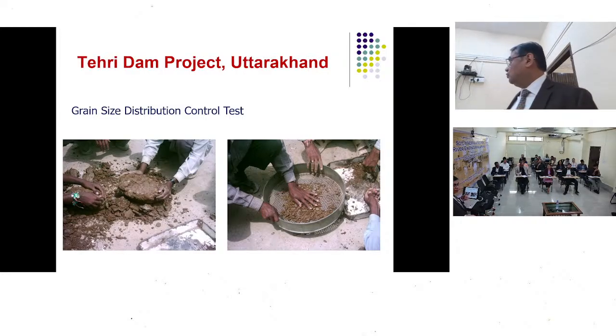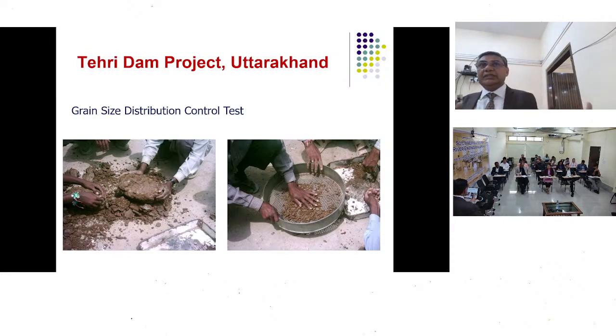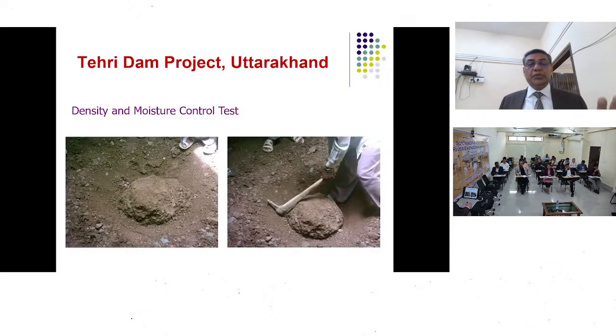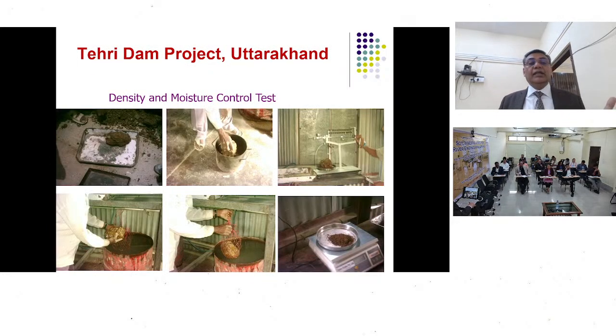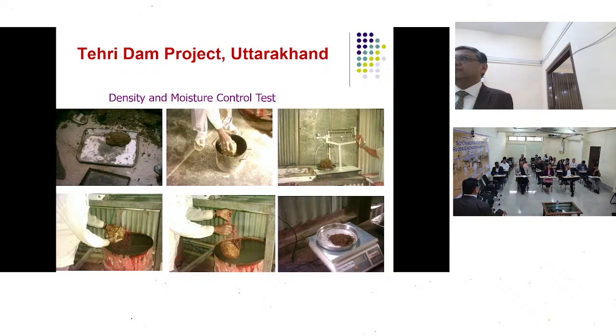We used to have two parts of it. One part was used for initial gradation, to determine the gravel percentage and the clay percentage, and then how to determine the in situ density. Then this piece or lump of soil was dipped in molten wax so as to have a thin layer of wax covering it, because we wanted to know its density by the water replacement method.